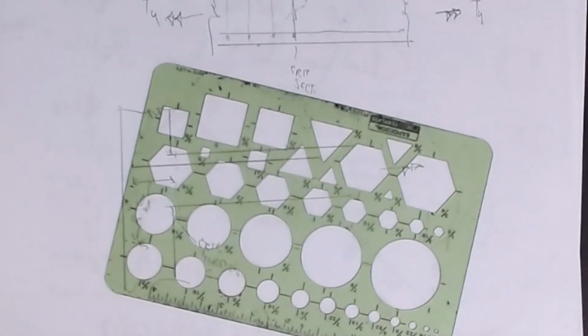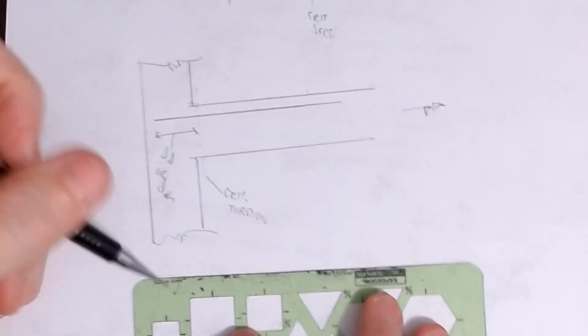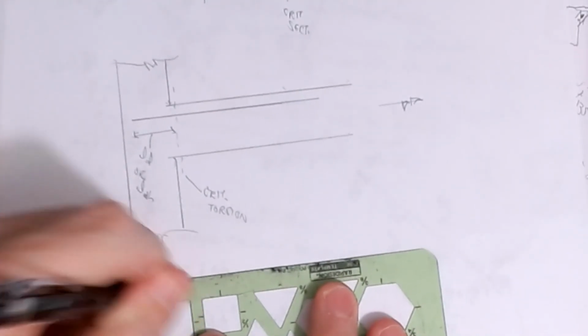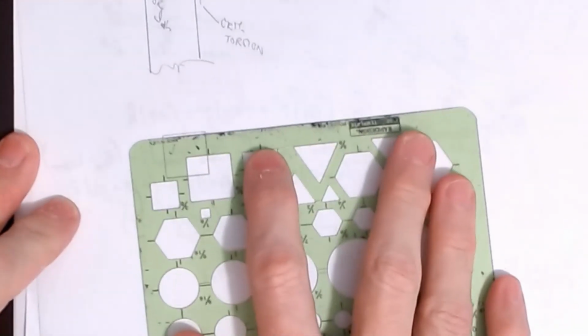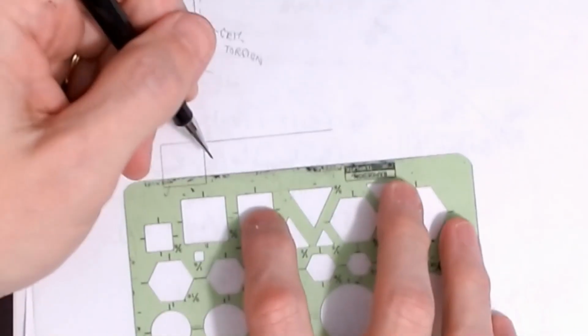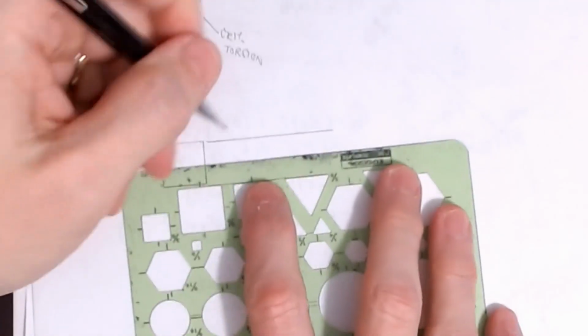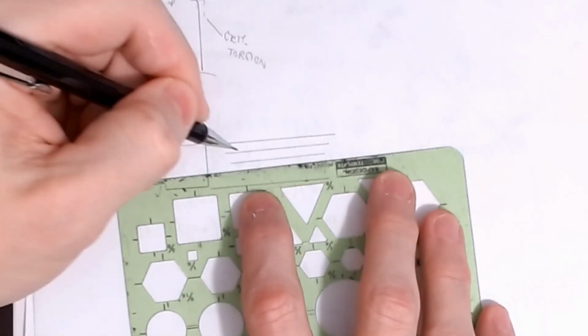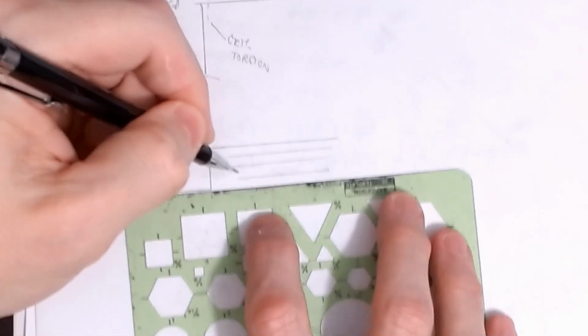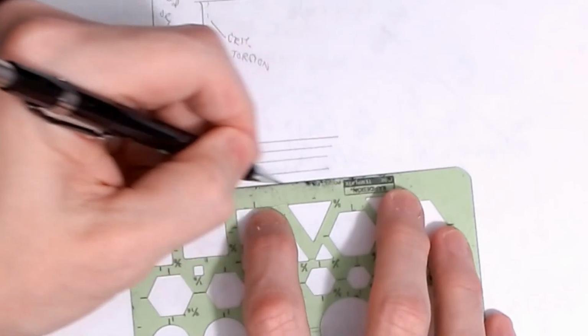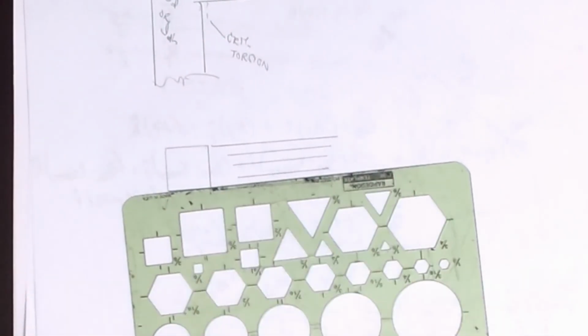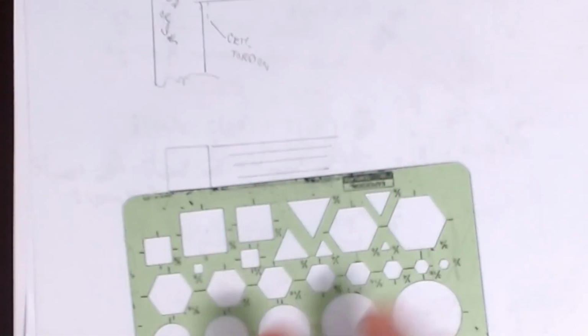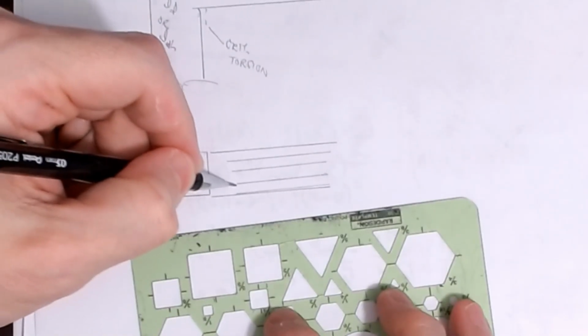What that means is, if I look at this in plan view, here is my column, and I have a beam coming in like this, consisting of, say, 4 longitudinal bars needed for torsion in a particular face. That requirement says at least 1/4 of those have to be continuous through the support.